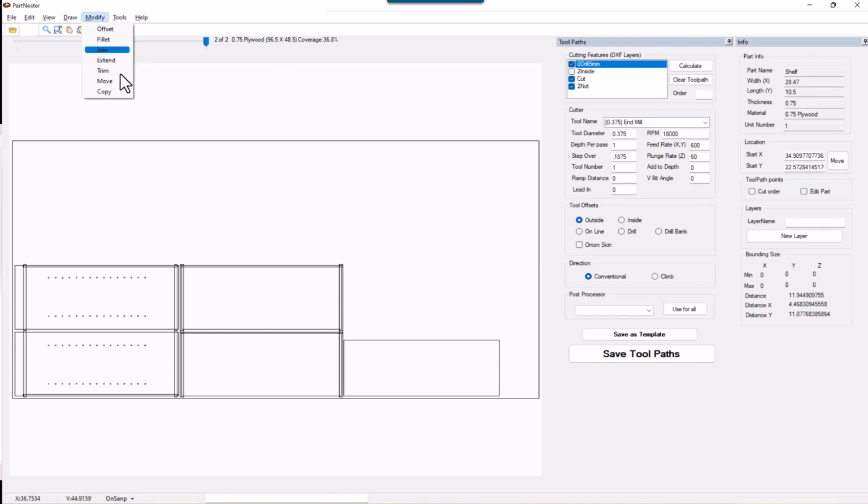The modify move is to move a feature from within that cabinet part. So first, when you select or click within any cabinet part, all of the features of that part are selected. We can see when we selected that top, the dados and everything have been selected, or selecting a side, we're able to see that the side, the dados, the shelf walls, everything has been selected.